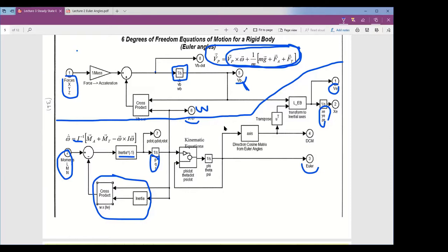All right, so what have we covered today? We did the gravity vector in Euler angles. We said we need to do the steady state equations next. So we've taken kind of a side road here to talk about, well, if you don't do the approximations to get the small perturbations in the steady state, you can actually do the full-blown set of equations, but you have to do it on a computer. And we're just integrating one particular input. If you want to analyze the total dynamics, we have to go to the equations and do Laplace transform.